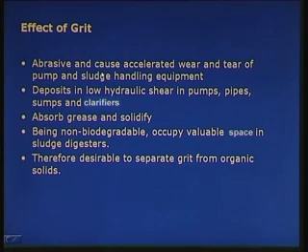So, we have several sludge handling equipments which go out of order because of this wear and tear. Then this grit deposits wherever it is possible. Where is it going to deposit? It is going to deposit most likely in places where there is low hydraulic shear, low flow conditions, in pumps, pipes, sumps and clarifiers.